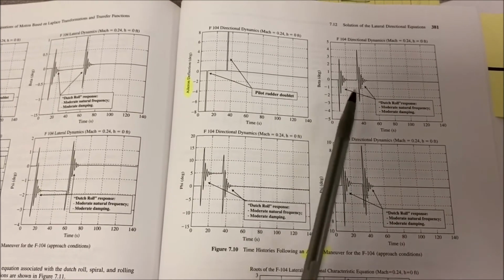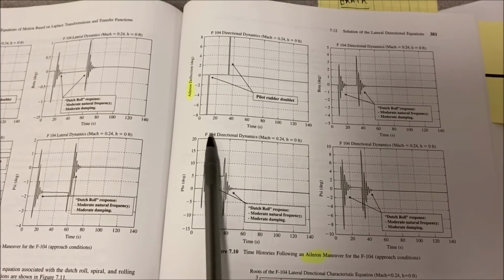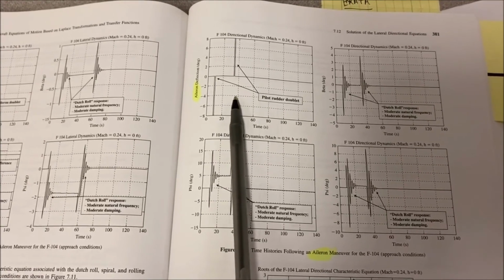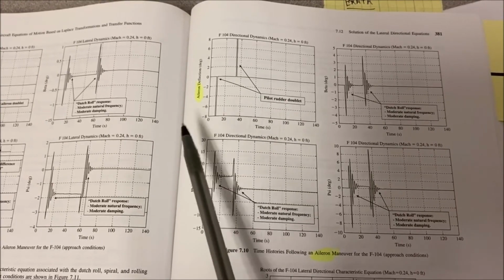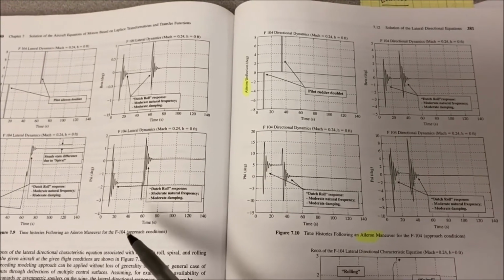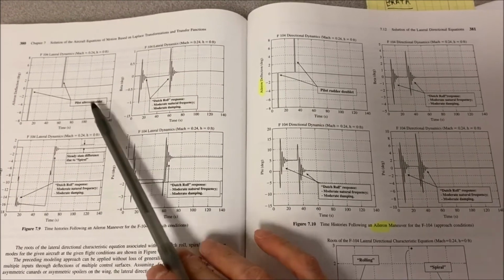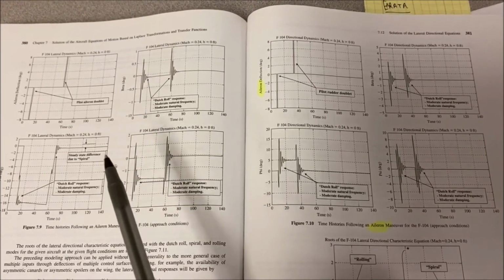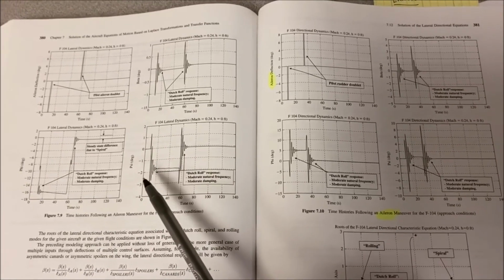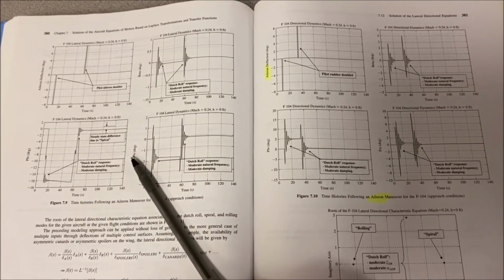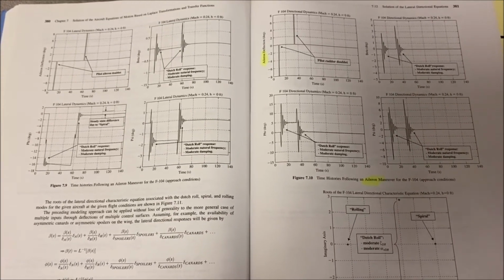And again, we can find functions of how beta, psi, and phi develop over time based on a known rudder deflection angle input, or some function of how the rudder deflection changes over time. So there we've seen two examples of, firstly, if we know the aileron input and we know the rudder input, then we can work out how the dynamics of these three other variables change in the same way as we did for the longitudinal sense. So now what we're going to do is just summarize all of that and put that all together a little bit.